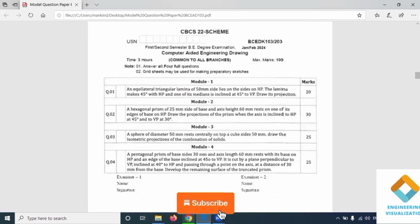You can see, an equilateral triangular lamina of sides 50 lies with one of its sides on HP. The lamina makes 45 degrees to HP and one of its medians is inclined at 45 degrees to VP. Here the angle of inclination is given with respect to the median. That means it is a beta angle problem. In this problem they have considered 50, but I will not consider 50. For showing purposes I will take 25 and then construct. So, beta angle problem. I'll show it in the SolidWorks software.